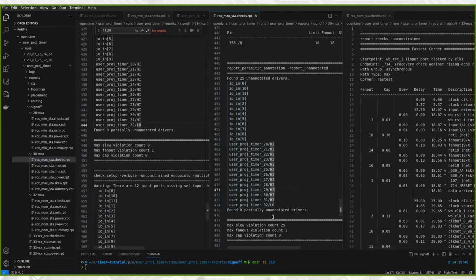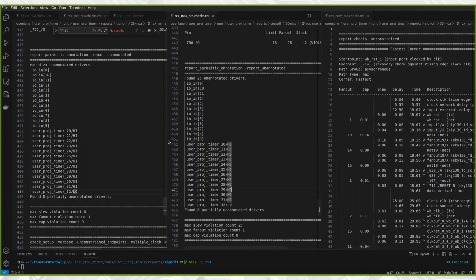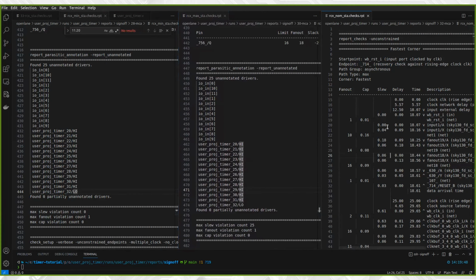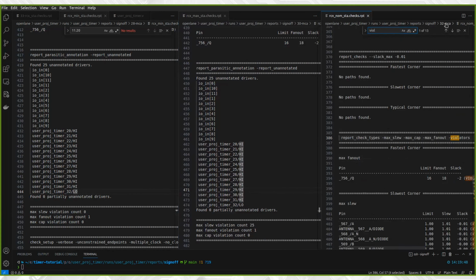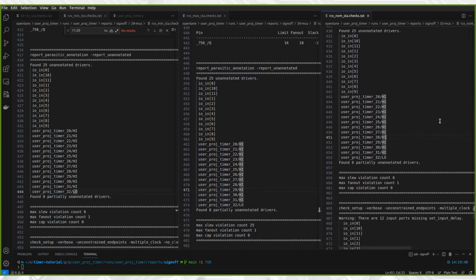Finally, the maximum fan-out is a soft constraint that is used to ensure that the design doesn't include huge fan-out on the nets. The net with the violation has the highest wire length and is connected to 9 antenna diodes. Therefore, the fan-out violation of 2 is acceptable since there are no other violations in the design.